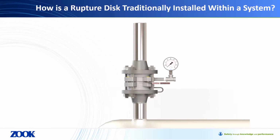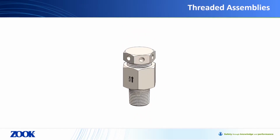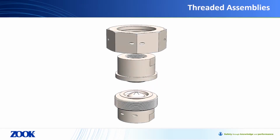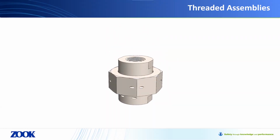A rupture disc is typically installed within a system using compression. This compression usually comes in the form of pipe flanges, a threaded connection, or a sanitary ferrule. To ensure the performance characteristics of the rupture disc and that rupture occurs at its intended point, we traditionally offer a number of rupture disc holders to install the rupture disc reliably and easily into the piping system. While the vast majority of rupture discs are installed in this method, improvements to performance can furthermore be made with a welded solution.